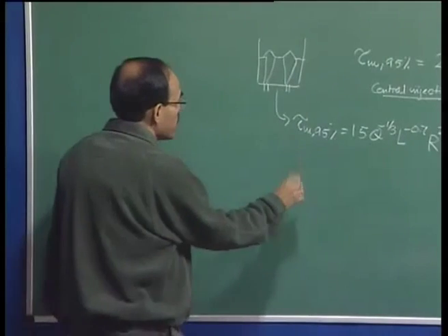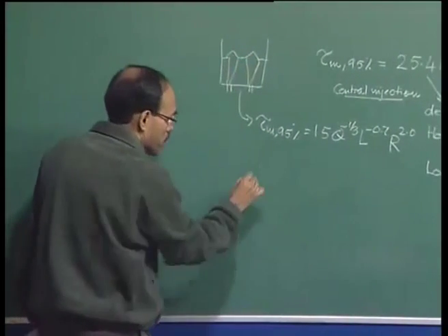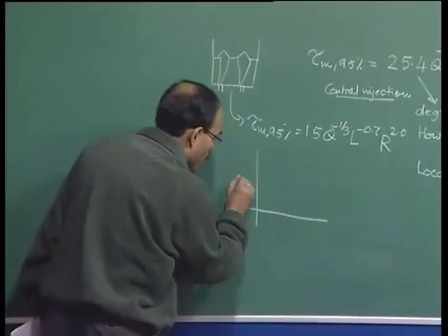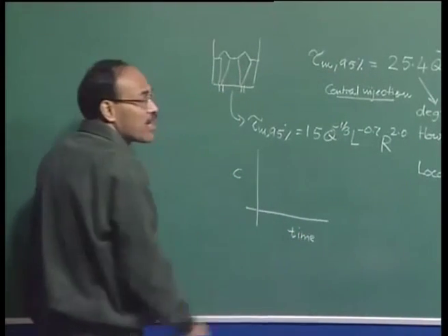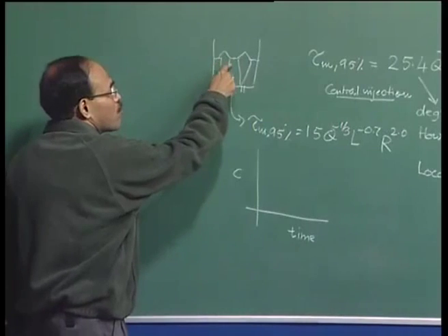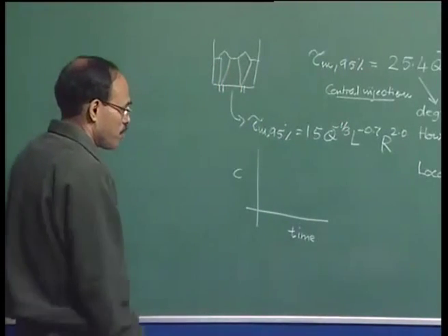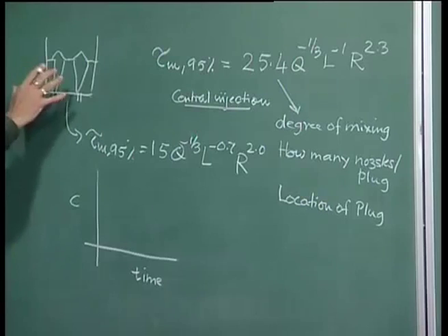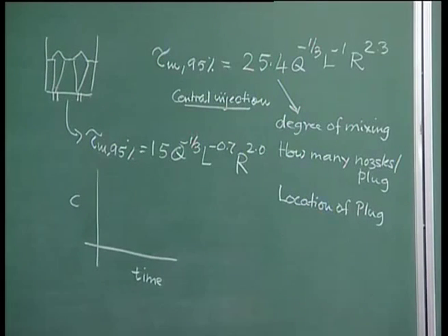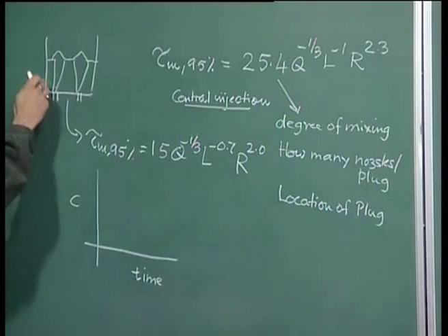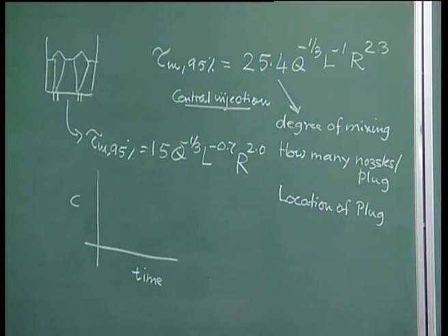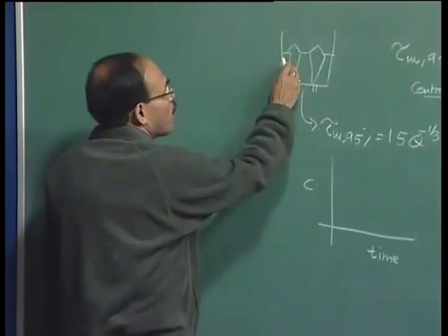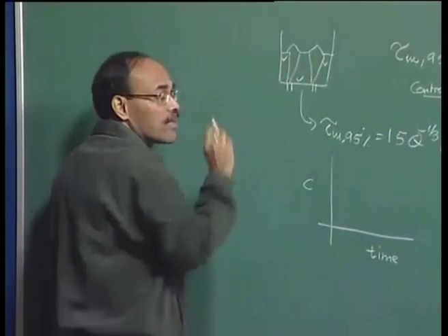Suppose you add a species into the system and monitor the concentration. So, we have concentration versus time at the monitoring location, which could be here, here, or here, anywhere in the system. Now, we talk about a reactor mixing time, which is important to us, because mixing time depends on position, since at various locations the intensity of fluid flow and turbulence are not identical. So, the rate of mixing will vary from one location to another in the system.